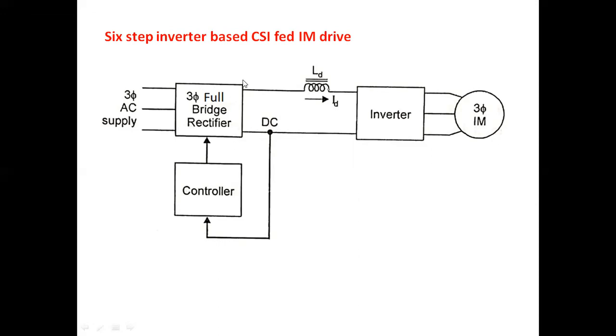External voltage control happens through the full bridge rectifier and controller. This voltage controller will set up the proportional current magnitude. This current magnitude now provides the variable current at the output. Variable current and variable frequency give constant I by F ratio control for this type of circuit.